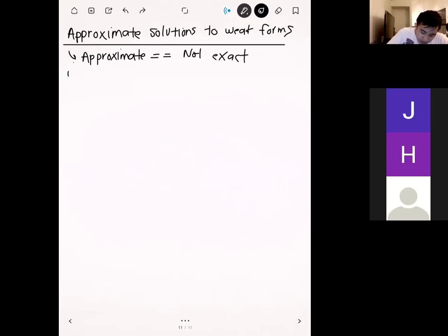This goes back to the very first day of class, when we talked about the general steps of the finite element method. The first step is that you have to discretize, so you break up your domain into a mesh. The second step, which I've been glossing over all this time, is to assume a form of the solution. One way that we're going to form an approximate solution is to first assume what the solution looks like.